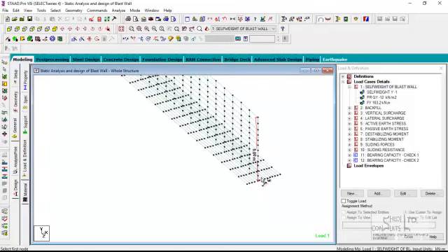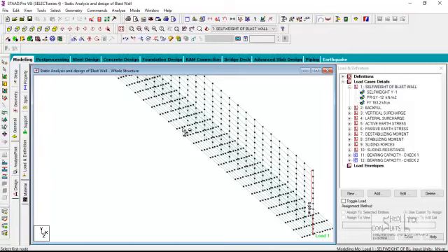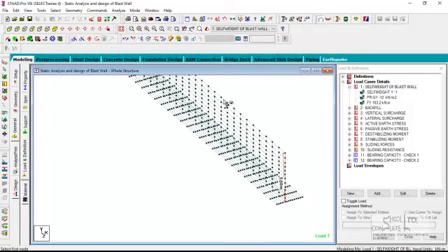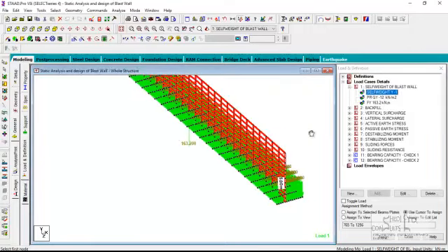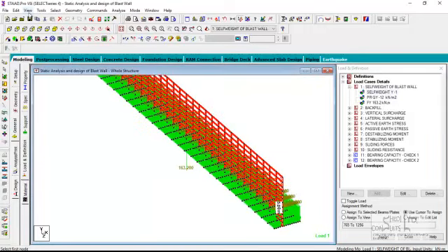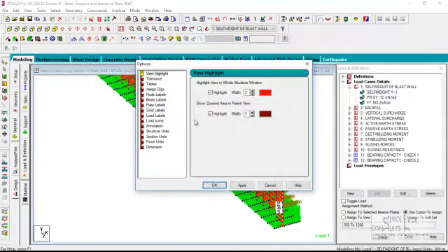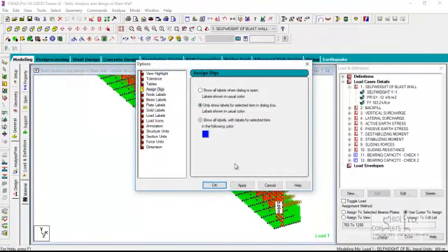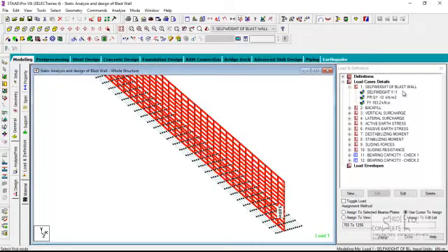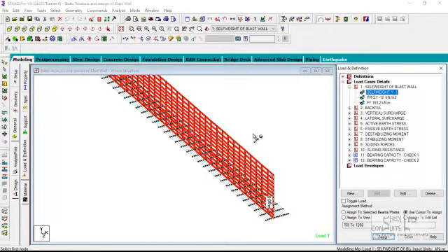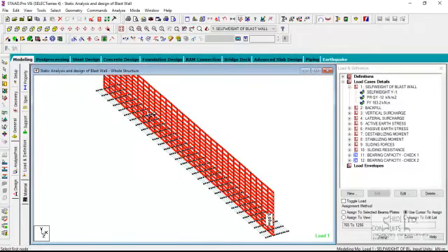You need to calculate a corresponding weight to 0.5 of the wall and then apply it as a counterweight, which will be subtracted from the weight of this entire wall. So if you look at the self weight, the self weight was specified. Okay, so the self weight loading, which is an automatic loading, was specified on the entire wall.